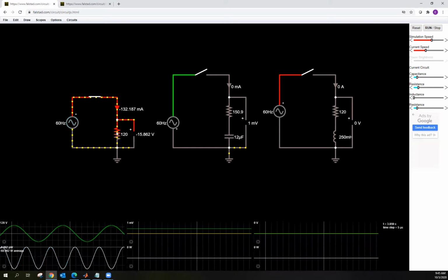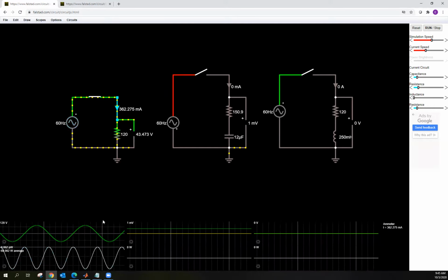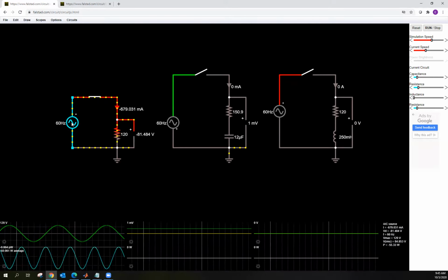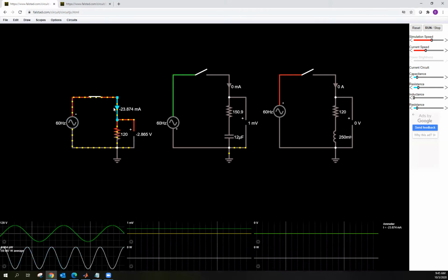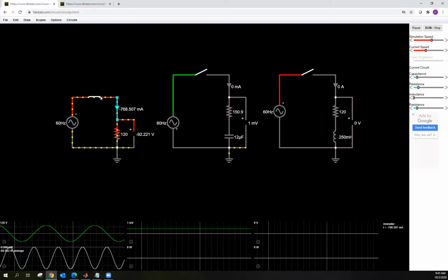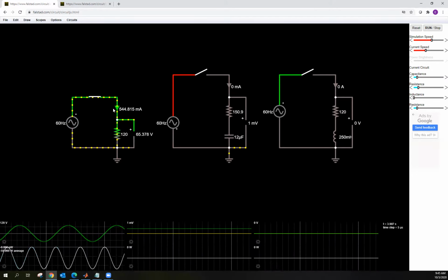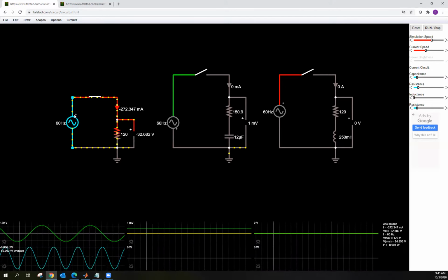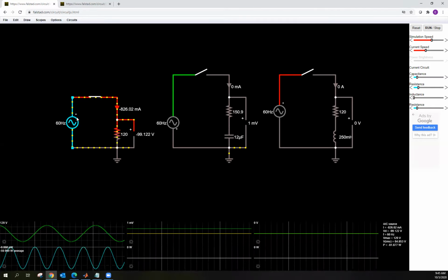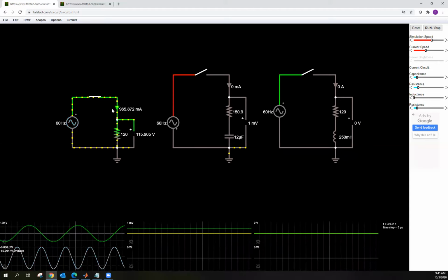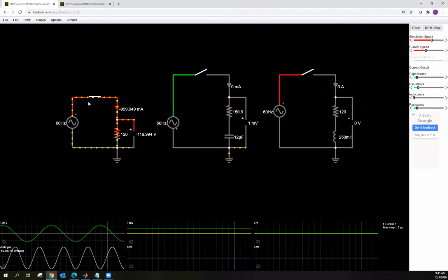It doesn't matter which way the currents are flowing, this power source is always delivering power, always negative. Look at the yellow current and the green and red voltage. When it's green, the current goes forward. When it's red, the current goes back. There's no lag, there's no lead in the current relative to the voltage, and so you have everything in phase.